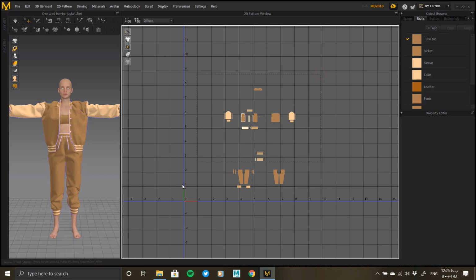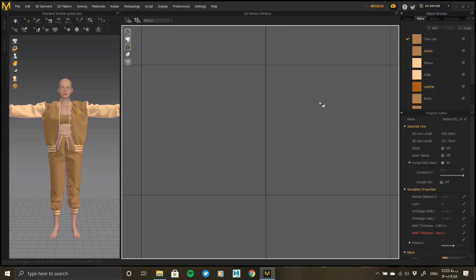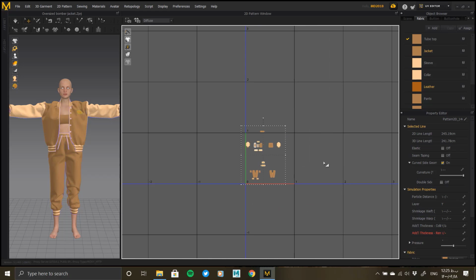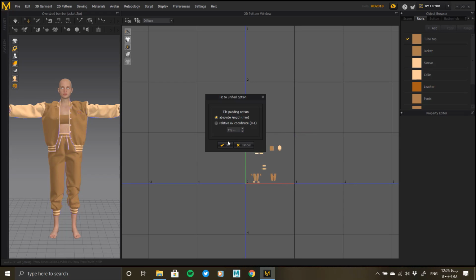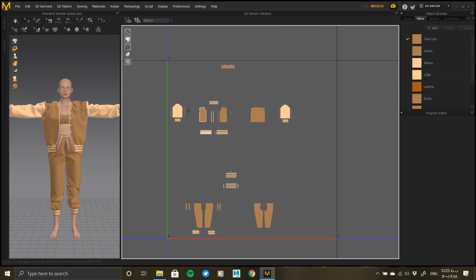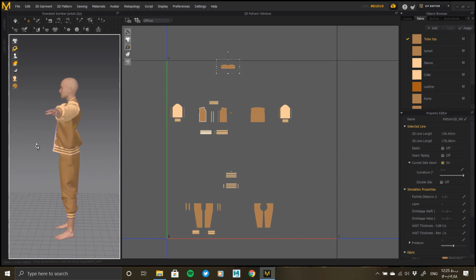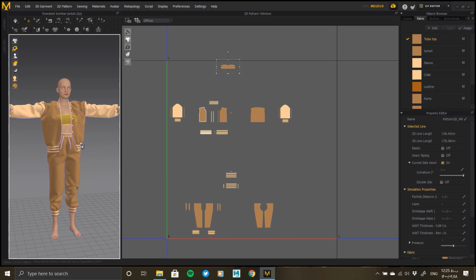direction. You can set the unwrap type based on UDIM, and set the whole clusters on 2 or more UV screens. In this case, each of the clusters will be placed in a larger size, and the texture will be placed on it with higher quality. The larger the clusters, the more UV space they take up, and the higher the quality of the material. Try to adjust the clusters, so that they are as large as possible in UV.